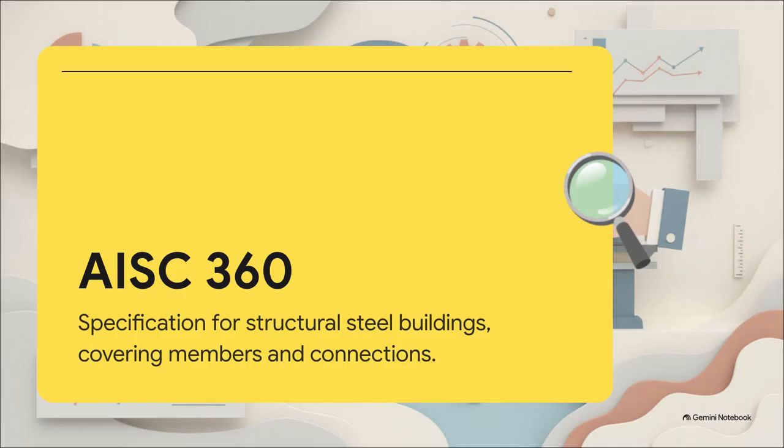Now, if you are designing in steel, the IBC mandates AISC 360. This standard handles all your typical steel member design: tension, compression, lateral torsional buckling, the whole shebang. But wait, if you're designing a steel building in a high seismic zone, like our California office example from earlier, a completely separate standard called AISC 341 kicks in. That one provides all the special high seismic ductility rules you're going to need.